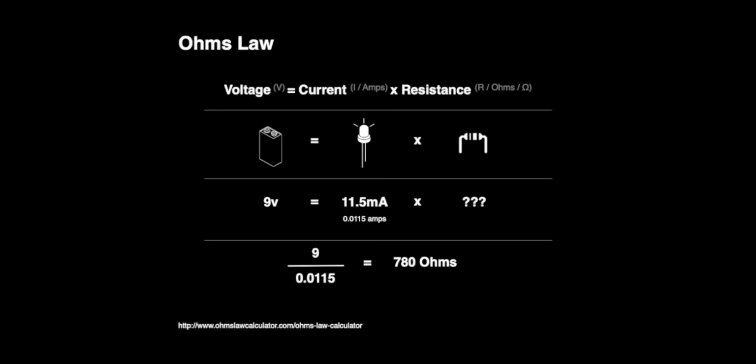To determine the amount of current that any component can handle, you want to look at the data sheet too, because it'll say on there a range of the current that particular component can handle. Sometimes you could go a little bit over, and it's not a big deal. If you go too far over and give it too much current, then it'll just burn out and fizzle, and it will destroy that component. That's the only potential issue, and eventually it could short circuit. So you just want to be careful of that.